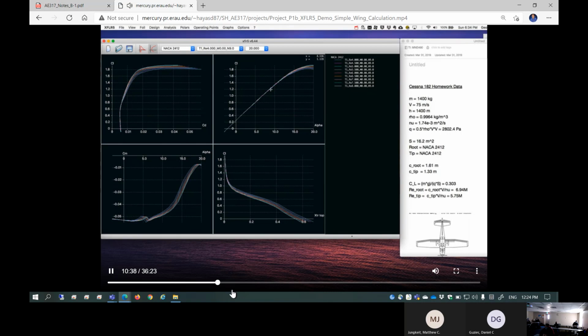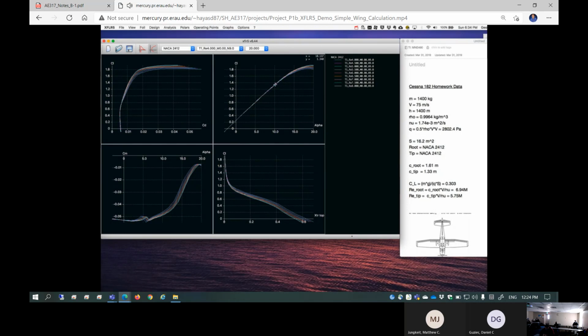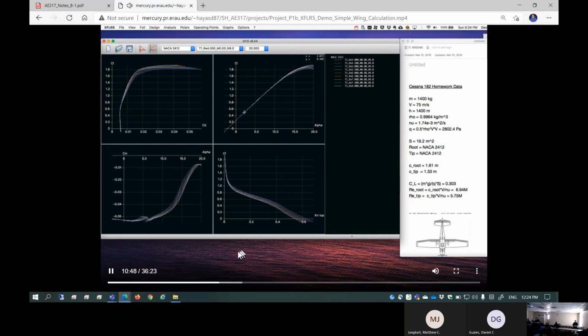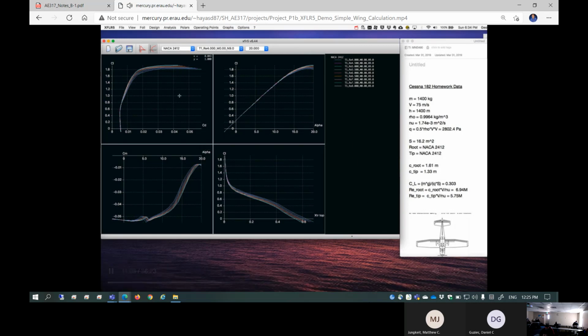And you can see our typical plot here. We have the lift, so that's a range of Reynolds numbers from 4 to 8 million by 500,000. In the linear part of the lift curve, and this is 2D, the curves are almost identical. They're on top of each other, and then they start to separate, and the higher Reynolds number can get to a higher lift coefficient. That's right. This is at the higher maximum angle of attack, before the flow begins to separate, so there's a decrease in lift coefficient beyond that.